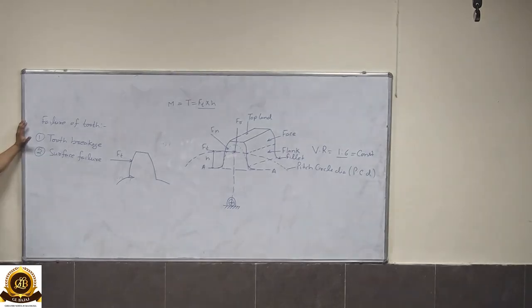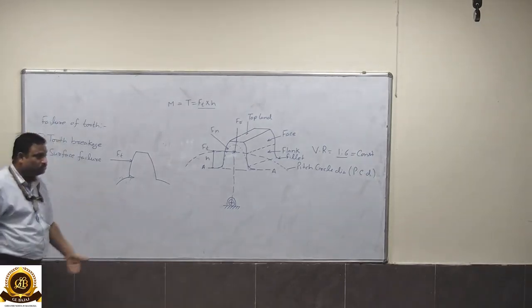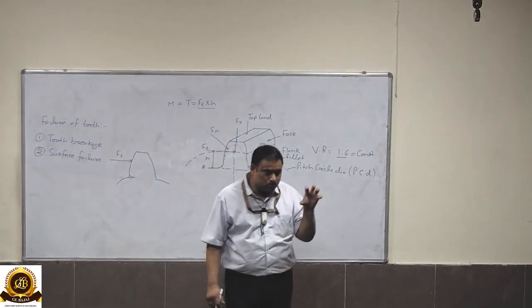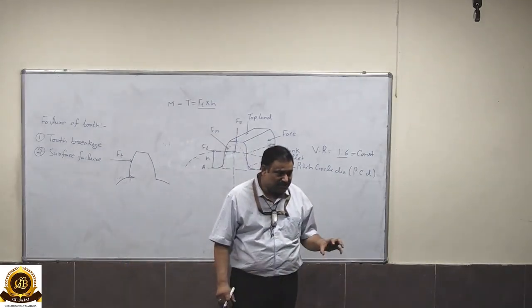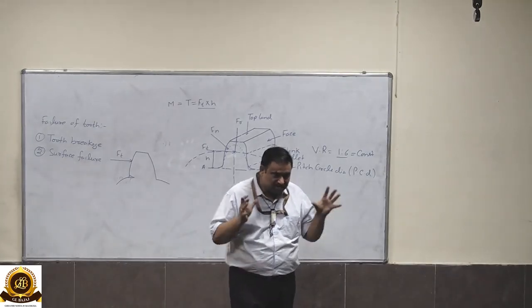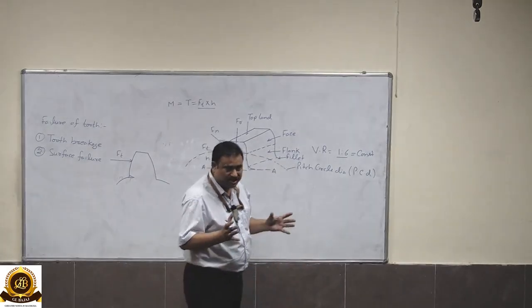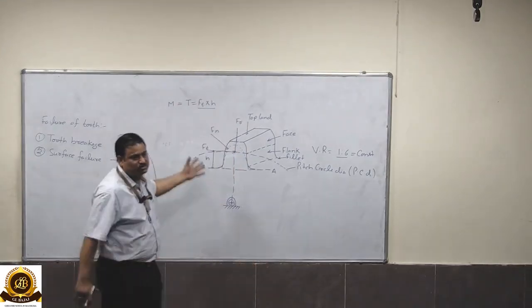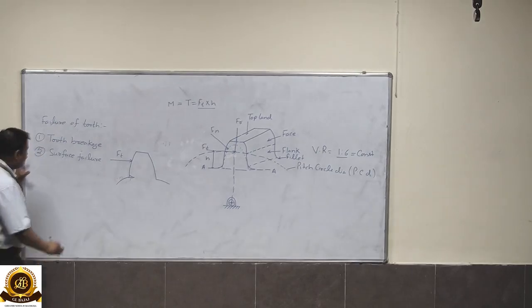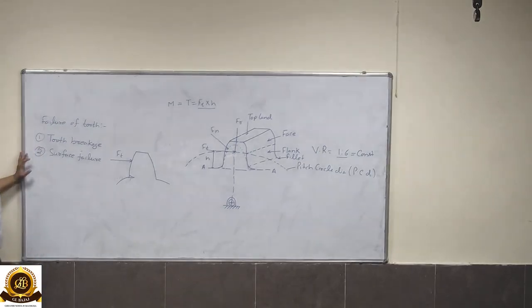So the purpose of this profile, which should be uniform throughout the section of the wheel, is that we have to form the tooth profile such that there is a constant angular velocity ratio. This action is known as conjugate action, and the profile is also called a conjugate profile. Conjugate action is required to transmit the exact or constant velocity ratio.